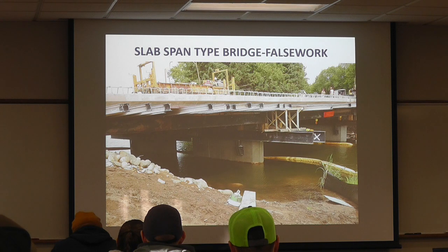So this is showing a configuration where they have something attached to this pier wall, maybe some kind of a through bolt, a bracket that's supporting these girders going this way, which in turn are supporting these beams or girders going this way, which in turn are supporting these, whatever those little members are, which in turn is supporting all the concrete load of the deck.